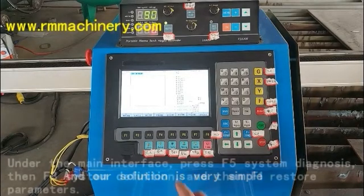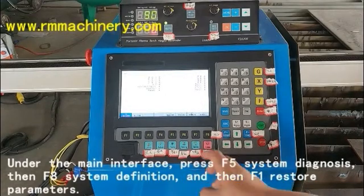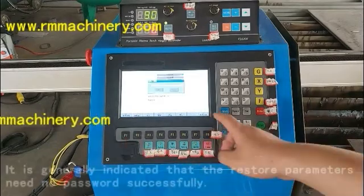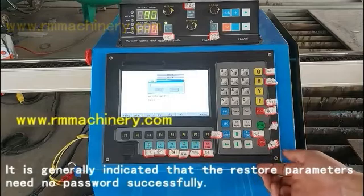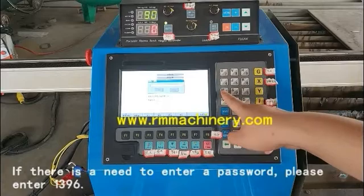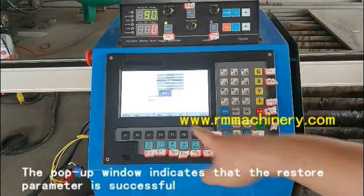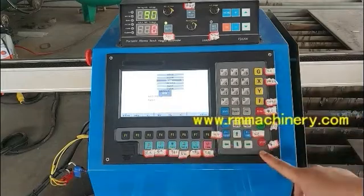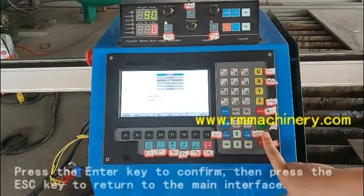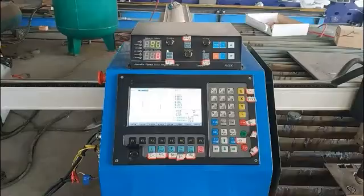Under the main interface, press F5 System Diagnosis, then F8 System Definition, and then F1 Restore Parameters. It generally indicates that the parameters are restored successfully without needing a password. If you need to enter a password, please enter 1396. The pop-up window indicates that the restore parameter is successful. Press the Enter key to confirm, then press the ESC key to return to the main interface.